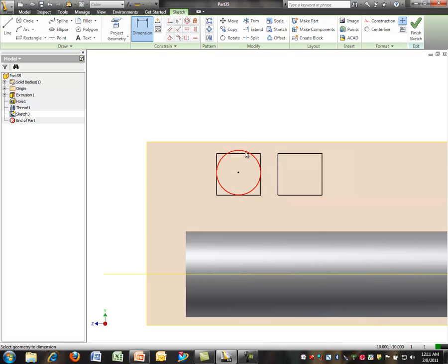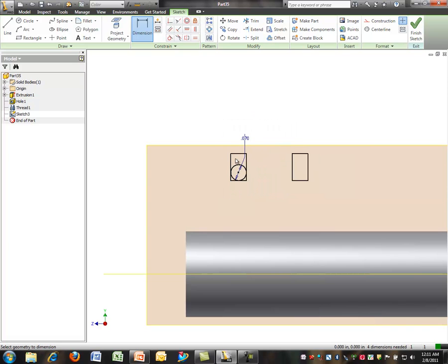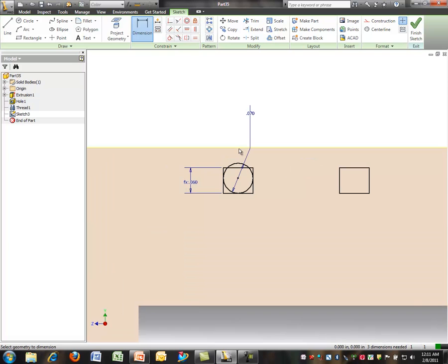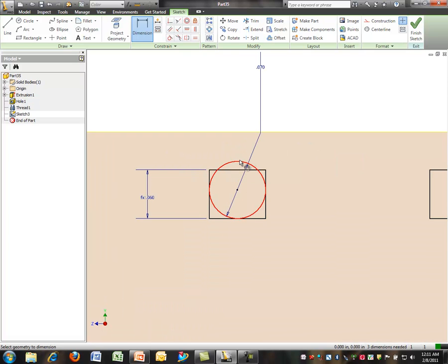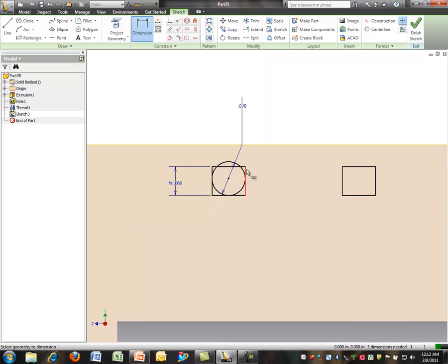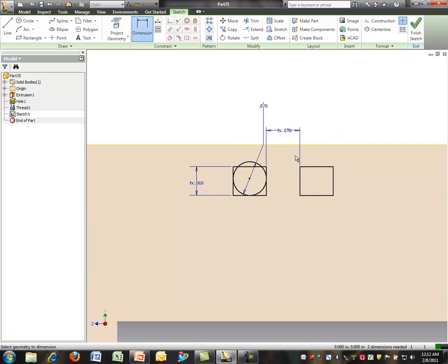And let's specify a diameter of this O-ring as 70 thousandths. And let's specify the depth of the groove as 85% of the diameter of the O-ring. Notice the formula that I'm using, so that now the groove depth allows 15% of the O-ring to stick out beyond. That'll help me give a good seal. And let's specify the distance between grooves as the same as the O-ring diameter.